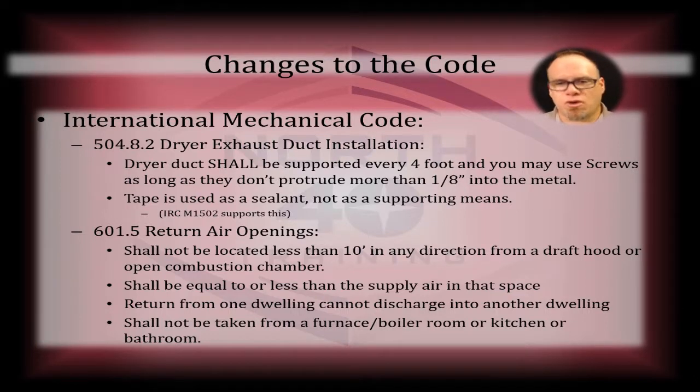So if you've got a furnace room down in the basement, you're not allowed to draw return air from that space. Okay? If you've got your furnace down in the basement and there's no walls, the inspector could effectively deem that entire basement space a furnace room. Then you're not allowed to draw return air from there at all. Now, that seems a little far-fetched, but let me give you a more practical example.